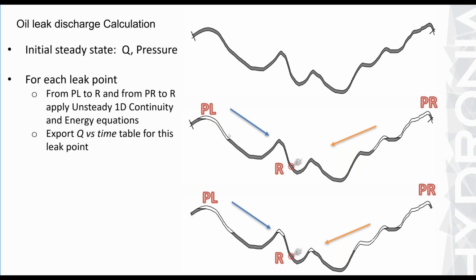Of course, the computation is much more complex because we apply the continuity equation for the pipeline for the points from the left to the spill location and from the right to the spill location. And these locations are based not only on the highest point on each side, but also because the initial flow can occur due to the pressurization from farther away, even if it's lower than the highest point here. That's why the volumetric computation is not accurate for this kind of computations.